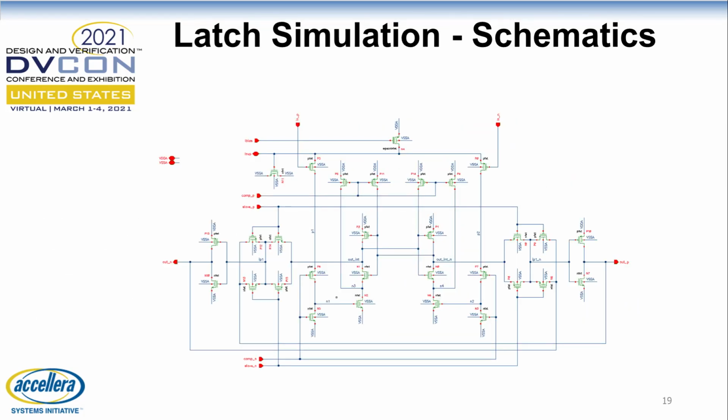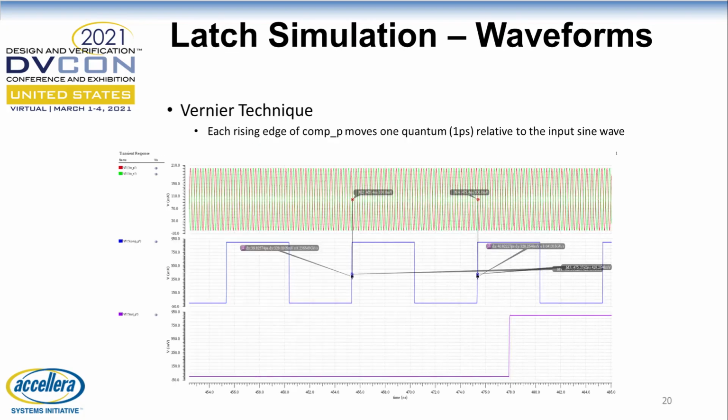The input signals are applied from the top, and feed the gates of 2 PMOS devices. The conductivity of these 2 devices will determine the direction in which the cross-coupled regenerative feedback circuit, the middle of the schematic, will flip. On the 2 sides, left and right, are level 2 digital latches for the positive and negative output signals. Let us now look into the waveforms.